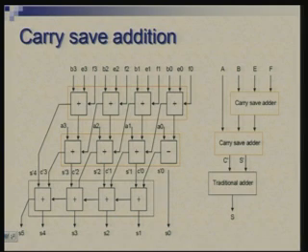So, now you can do this, this is called carry save addition, because we are saving carry for the next stage. You can do this up to some stage, but the last stage has nothing else to fall back on. So, in the last stage carry has to propagate, which might give an impression that you would require one extra stage.